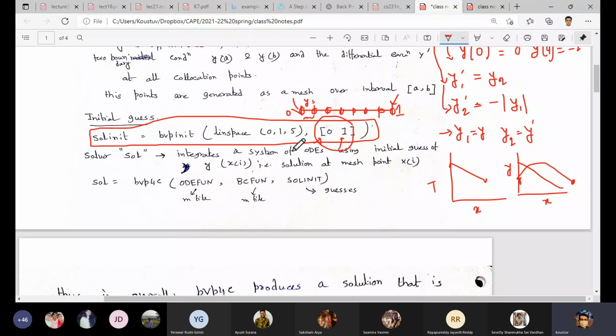If you know the physical picture of your problem, you can speculate or guess that the temperature would fall, or concentration would rise, or velocity would decrease in that profile. So in that sense, you try to give the initial guess by satisfying one of the boundary points. That actually makes the initial guess structure, and that is one major step of writing the script in the main file.